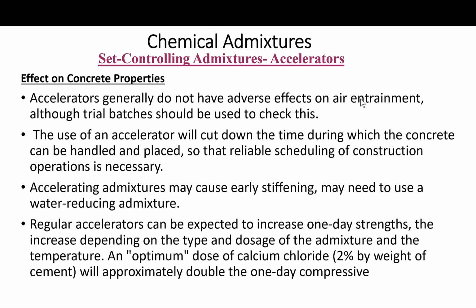It must be remembered that the use of an accelerator will cut down the time during which concrete can be handled and placed, so that reliable scheduling of construction operations is necessary. And again, you have to remember this. If your concrete is being dosed with accelerators, make sure you know when to order the concrete and to place it quickly before it's too late.